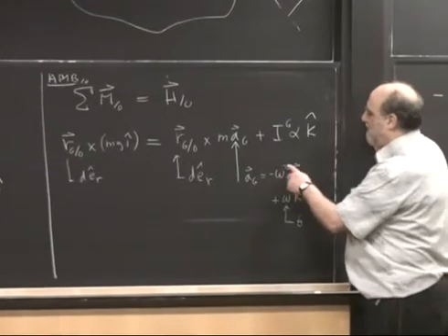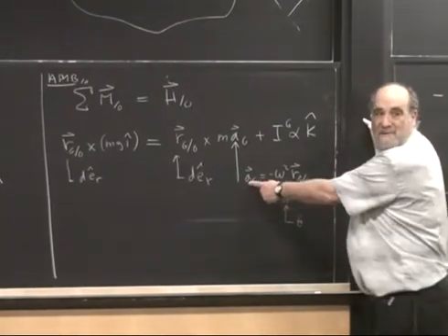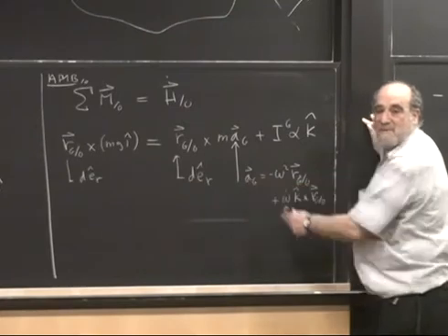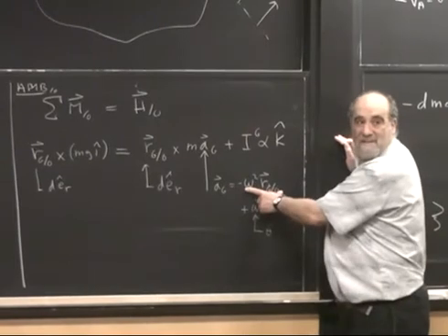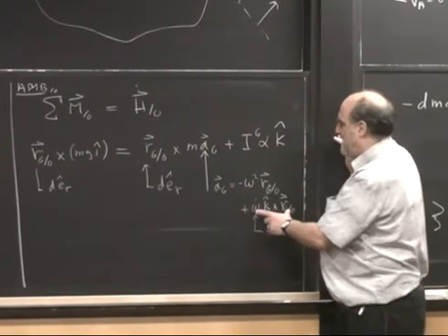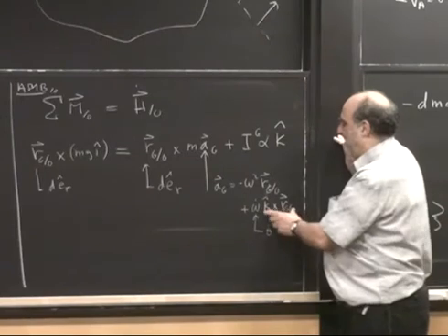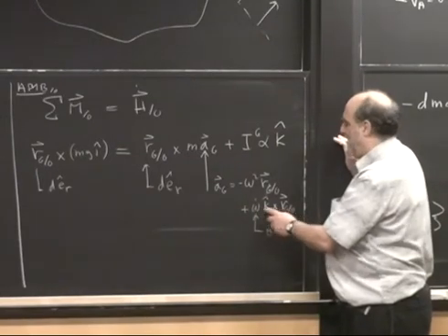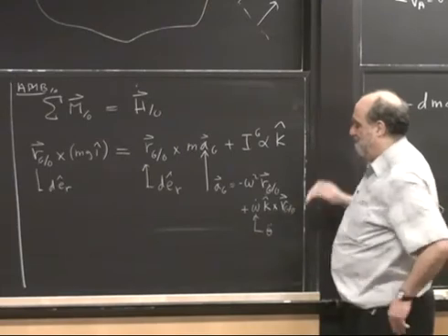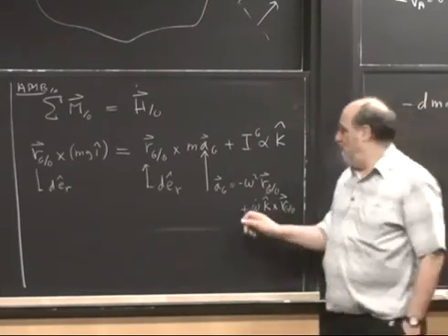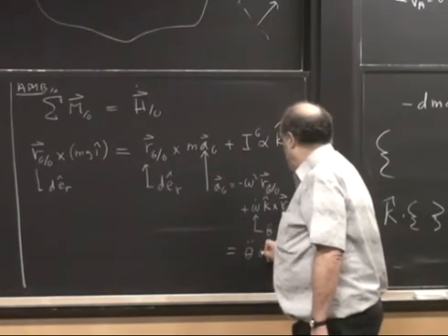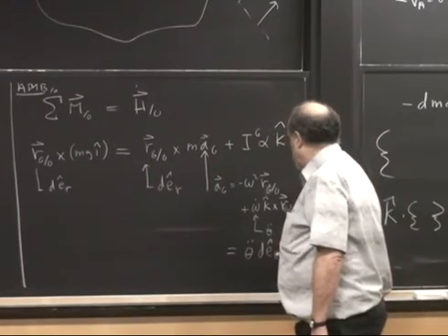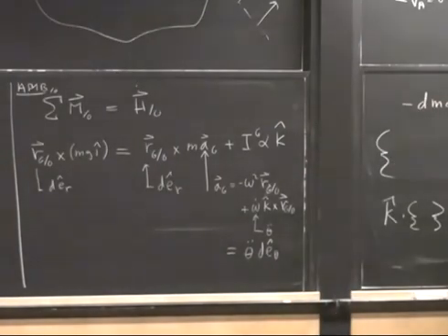Okay, this is just the polar coordinate formula for acceleration that you've used all along. Polar coordinate acceleration says we have a minus theta dot squared r. That's a radial acceleration, and a tangential acceleration, which was in the e theta direction, which was theta double dot times the radius in the e theta direction. So this whole thing here, if we like, is theta double dot d e theta. Okay, any other questions?